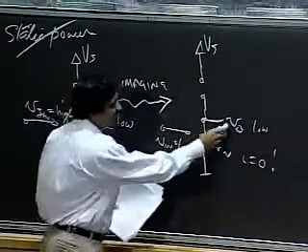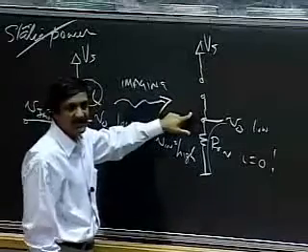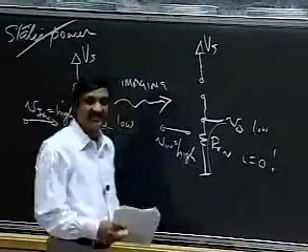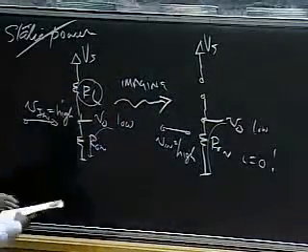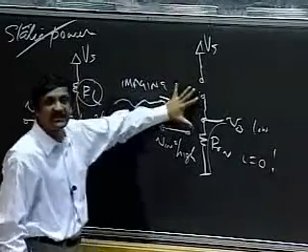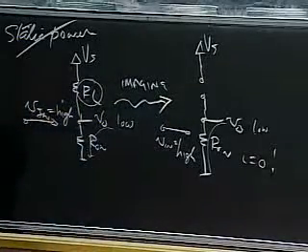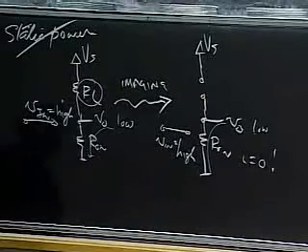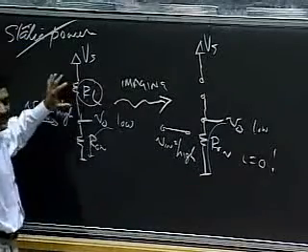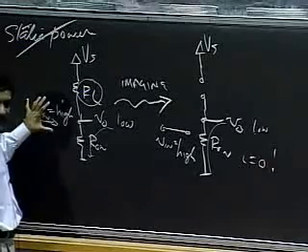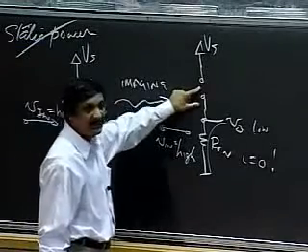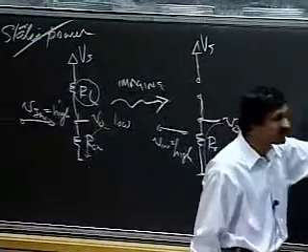Out here, I have a direct connection to ground and nothing to the power supply Vs, and therefore I have a nice solid low. So the question is, can I get this situation? That is the key insight. Imagine that somehow, when this was high, I could get this to open up, much like when this was low, I got this to open up.